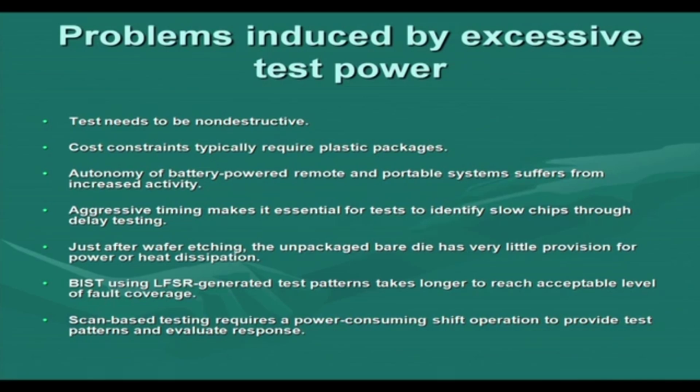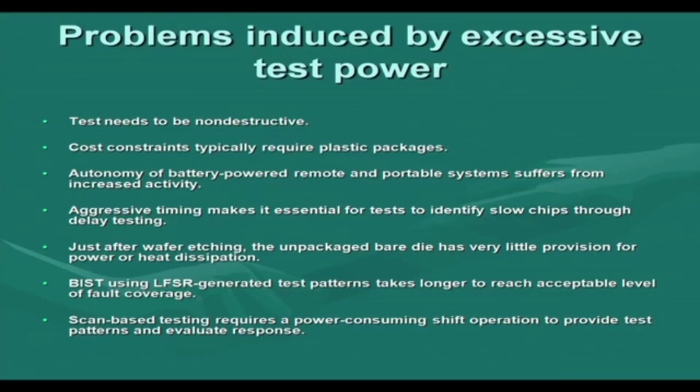Then, if we look into the test techniques that we have seen so far, like the BIST. In case of built-in self-test, we generally use some LFSR to generate a large number of patterns. In a fault simulation process, we can run the LFSR, see the patterns that are getting generated, and try to see what faults are getting covered by individual patterns. Then, after running the LFSR for a good amount of time, we may reach the sufficient level of fault coverage that we are looking for, and then we stop the LFSR. So, the LFSR has to be run for so many cycles.